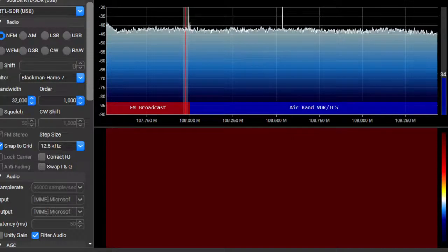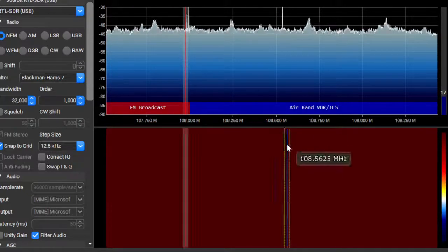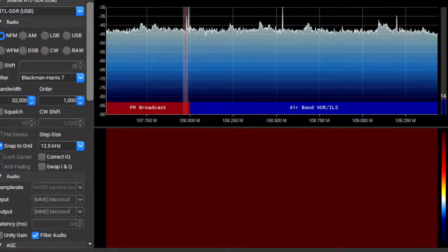All right. So the wires are really shaky. I'm gonna show you how the wires are connected. When you do yours, please make sure you solder them, or you use a more stable connection. So let me just turn on the camera so I can show you what I mean by that. So you can see the wires and the antennas, they're just hanging. They're not soldered. So make sure you solder your wires and don't have your batteries hanging this way.